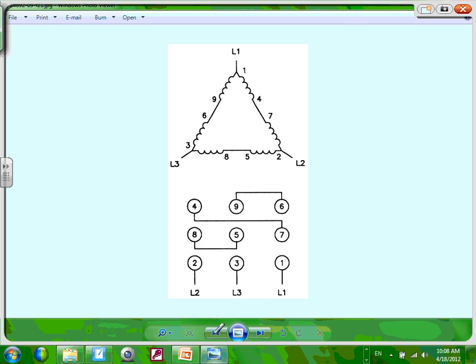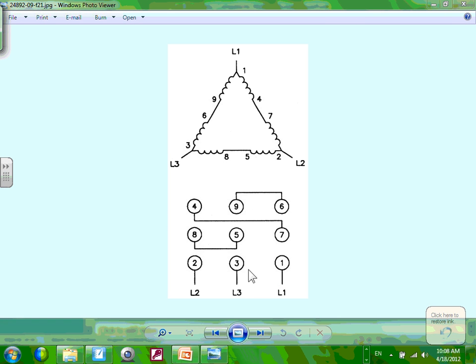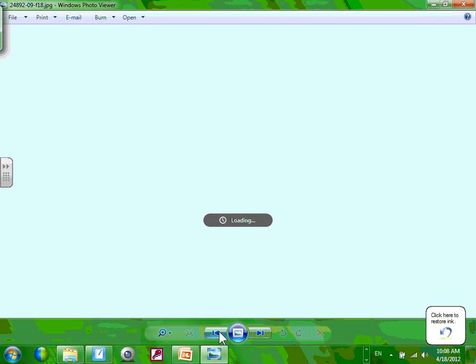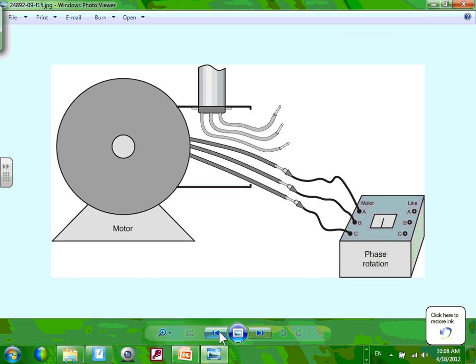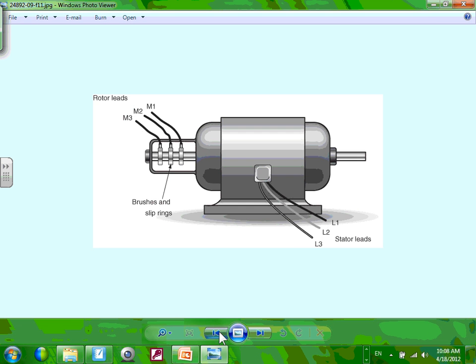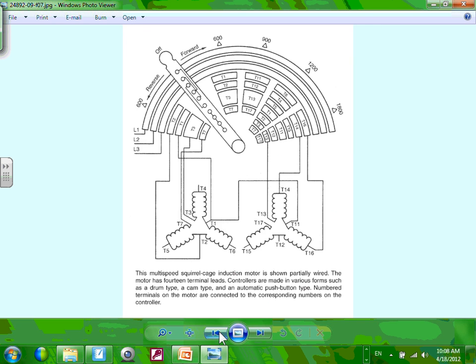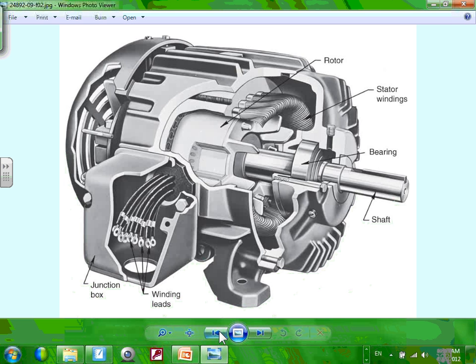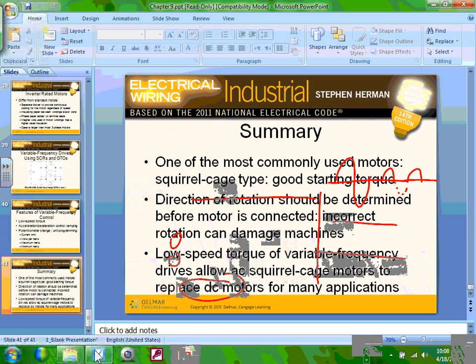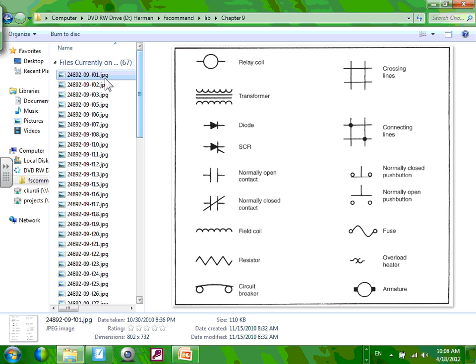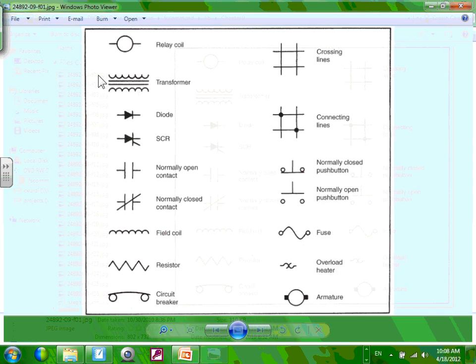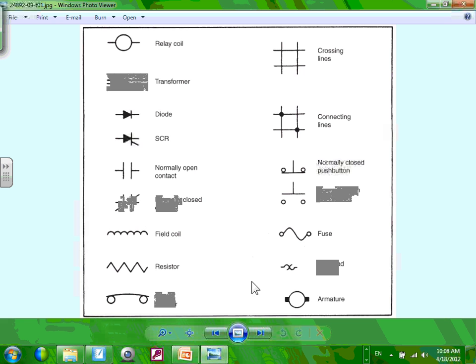Chad, go ahead. Do VFDs have to be located close to the mechanical equipment on the roof, or can they be in an electrical room? Close to the equipment. The best location for a VFD is close to the equipment. If you can't, they do kickbacks of harmonics and so forth. So the best location for them is right next to the equipment. If you can't or will not, then they put filters way at the end.